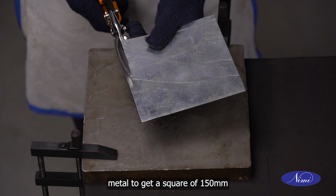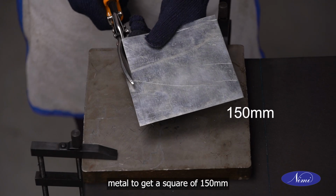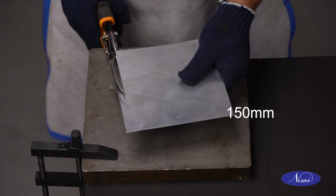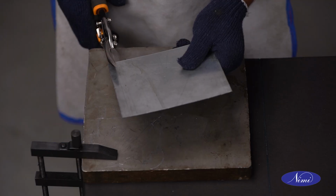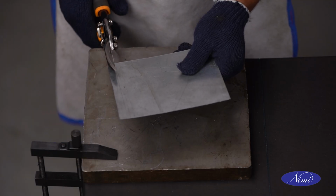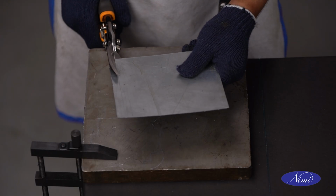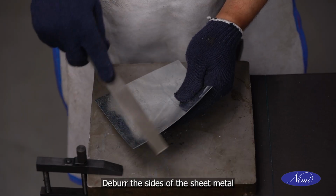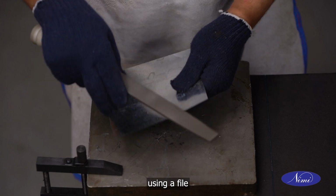Cut the sheet metal to get a square of 150 mm using a snip. Deburr the sides of the sheet metal using a file.